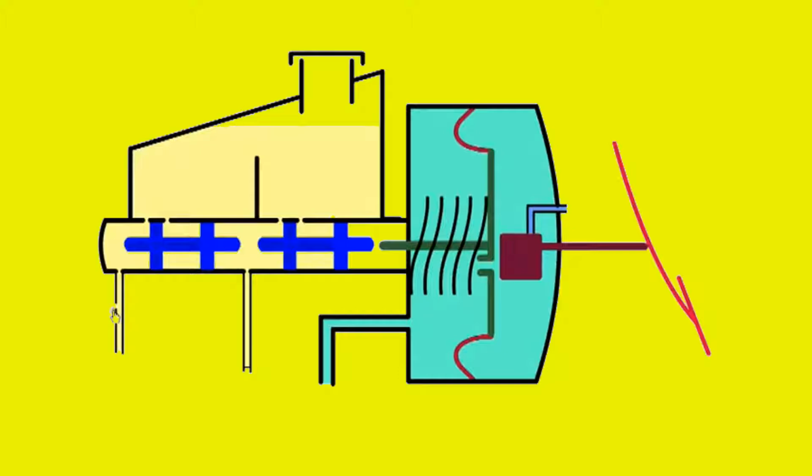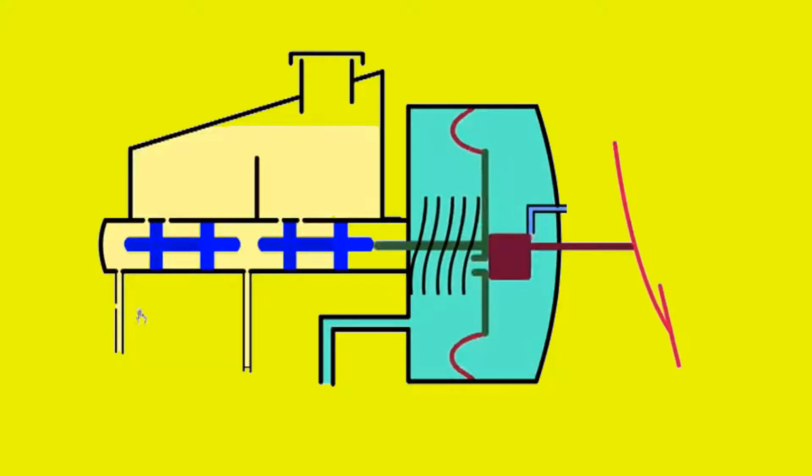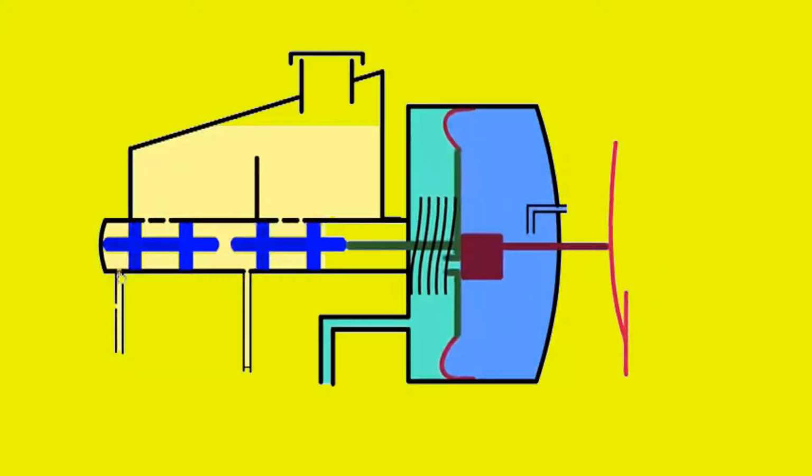If we have a leak in the left-hand circuit, its piston will move all the way to the left, as there is no restriction. The brake pedal will depress further, but will eventually build pressure in the other circuit. The division in the plastic storage tank ensures that if we have a leak in one circuit, we will not lose all the fluid in the other circuit.